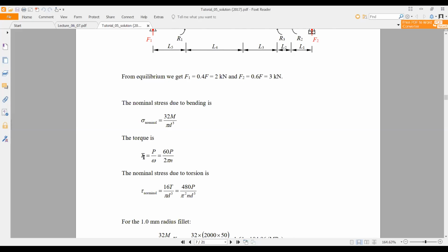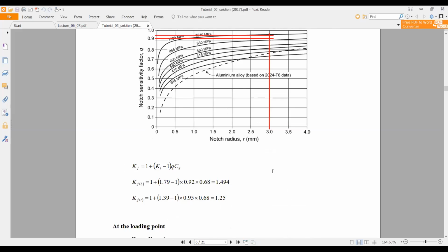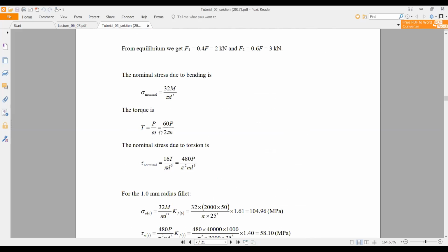When you use that, here you can see omega, they provide as RPM. You need to substitute not RPM but radians per second. If you know the number of cycles, it is N, so omega equals, you know how to find it from RPM. RPM means rounds per minute. When you convert to radians per second, it is just unit conversion. One round means 2π.